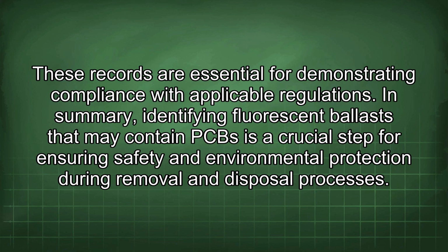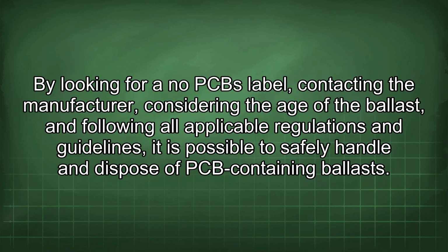In summary, identifying fluorescent ballasts that may contain PCB is a crucial step for ensuring safety and environmental protection during removal and disposal processes. By looking for a no PCB label, contacting the manufacturer, considering the age of the ballast, and following all applicable regulations and guidelines, it is possible to safely handle and dispose of PCB-containing ballasts.